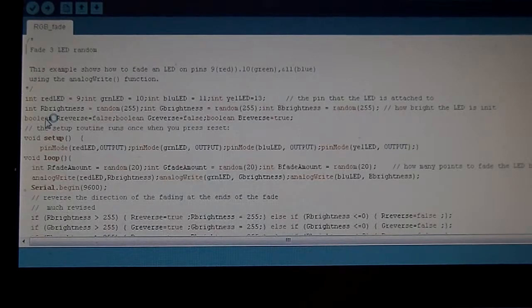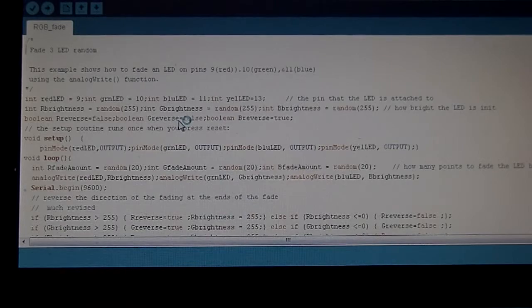When you get to a certain number in Arduino that's too big or too small, it kind of folds over on itself. It can only go to a certain number. I should look that up and tell you what it is. At any rate, the variables weren't behaving. They weren't smoothly going up and then smoothly going down. At one point I had them smoothly going up, but then they were going down all at once, et cetera, et cetera. It was really hard to get this all working right.